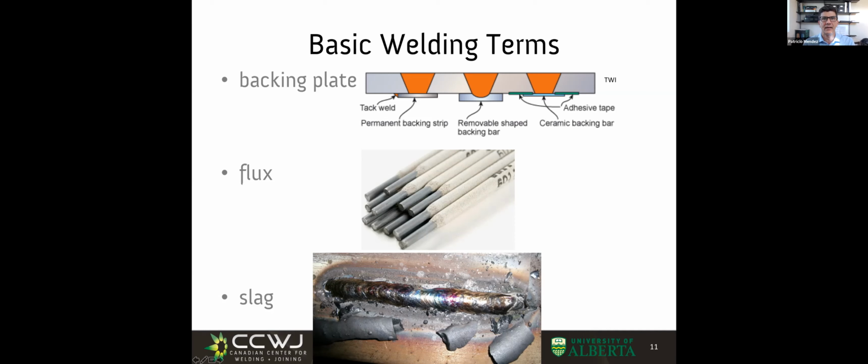We call it slag. And if you ever saw a welder in action, when they come with a hammer and start hammering the weld, what they are doing is chipping off this slag that is a solidified glass, right? It's a ceramic. So it chips off and goes away, and here you get your weld, right? So same thing. Before you melt it, you call it flux. After it melted, you call it slag.